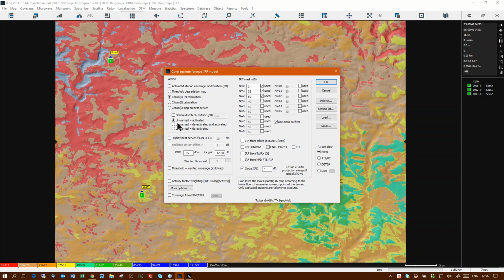What we're looking at, the default settings when it pops up. Here we've got coverage, and then there's the sum of the interference plus this thing. It's not noise. It's the channel, adjacent channel. So you've got a 20 or 32 dB attenuation on the adjacent channel, 50 dB attenuation on the next adjacent channel, and you can add more if you want. But that is channel based, so that you've got a 25 kilohertz system. These are 25 kilohertz Nyquist blocks.